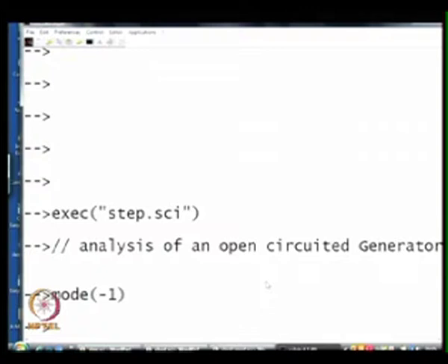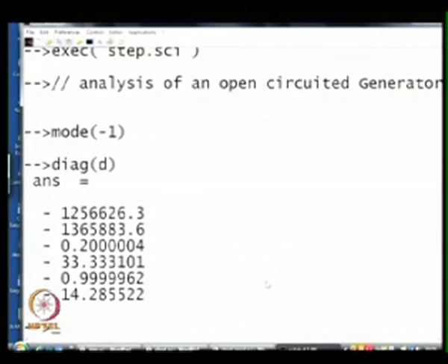Before I show you how the time response looks, what we first will see are the eigenvalues of the matrix A. If you evaluate the eigenvalues, we are getting two large numbers. These large numbers are indicative of something happening very fast. They arise because we have chosen RL to be a very large number, which results in very large negative eigenvalues. So this transient dies down very soon.